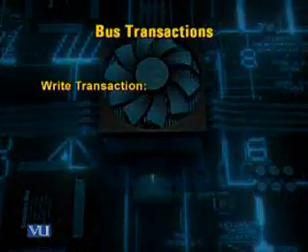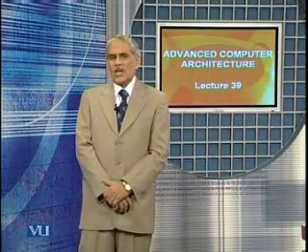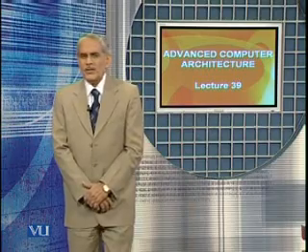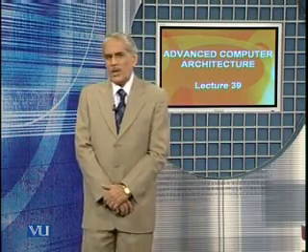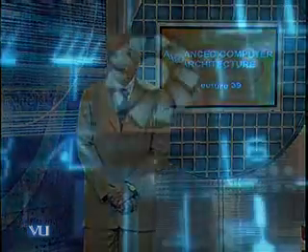And in response to this, the memory sends the data and it deasserts a signal which is usually known as the wait signal. Whereas for the write transaction, the address and data both are sent down the bus to the memory together with asserting the write signal. The memory stores the data and deasserts the wait signal.